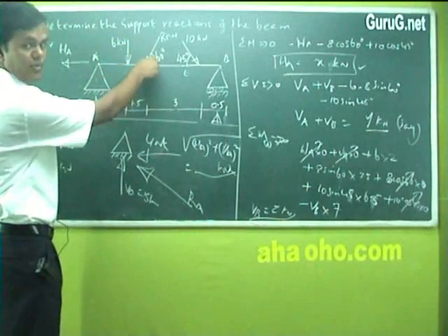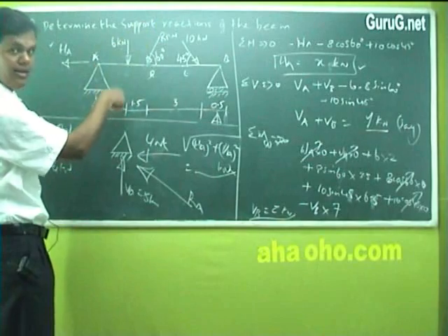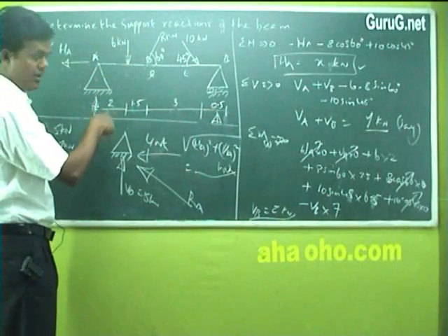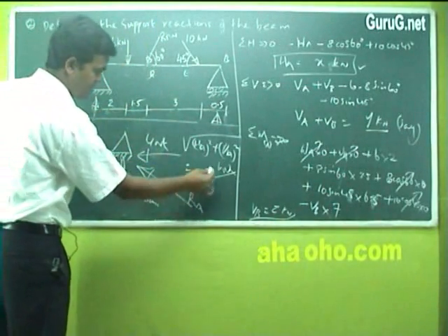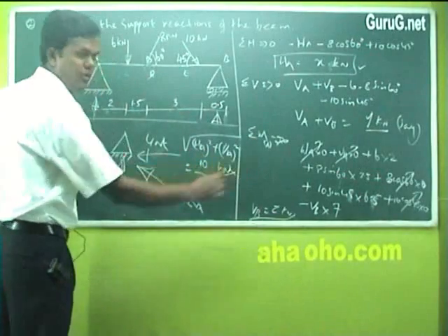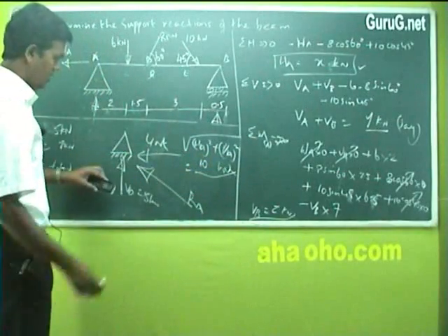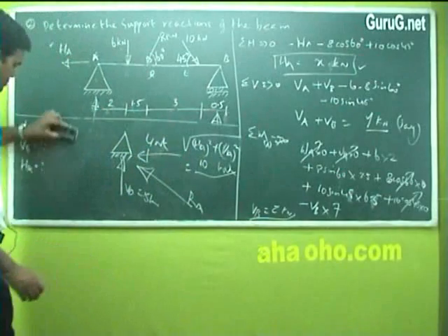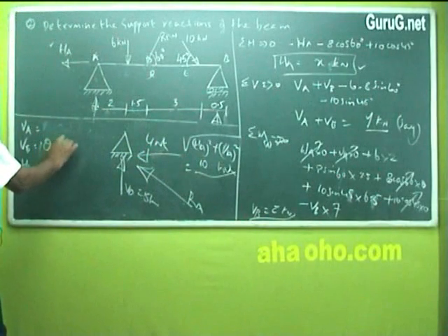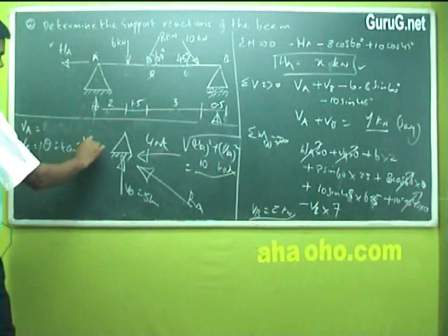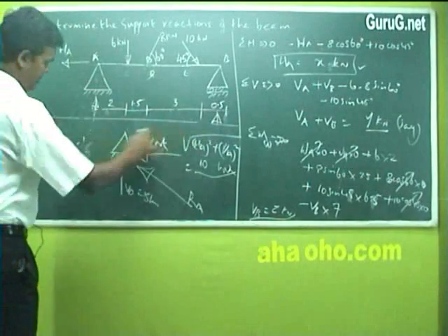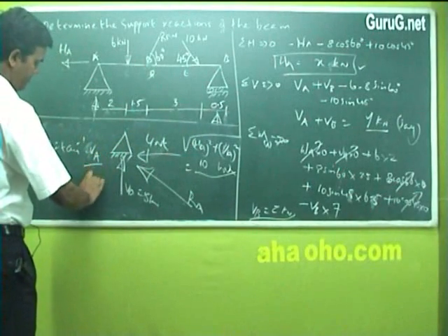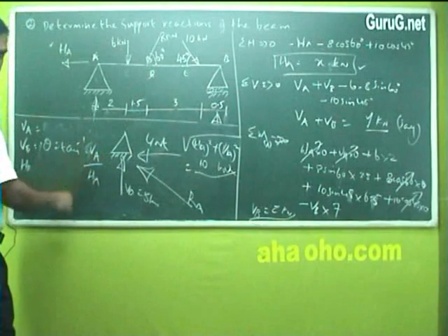See, this angle indicates at what angle the force is coming down. Like this is the resultant reaction, say suppose 10 kilonewton is your answer. I'm just giving an example. How to find its angle? Again the same procedure. Theta is equal to tan inverse of VA by HA, vertical by horizontal.